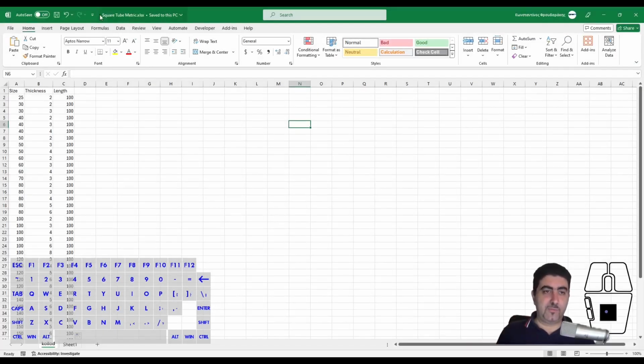Also, please note that the name that you give to your Excel file is going to be the name of the part that you will create inside the toolbox, plus there needs to be one Excel file and one Alibre part with the same name for them to talk to each other, right?